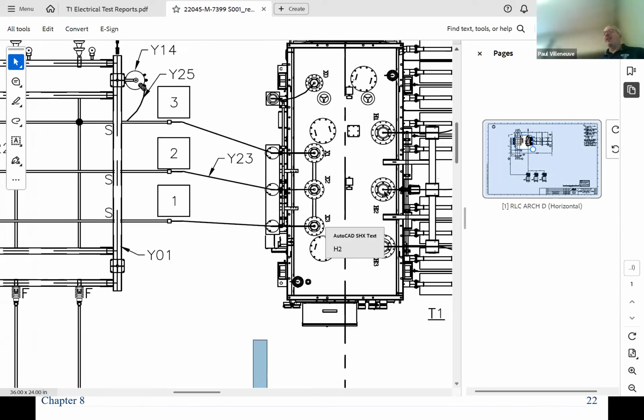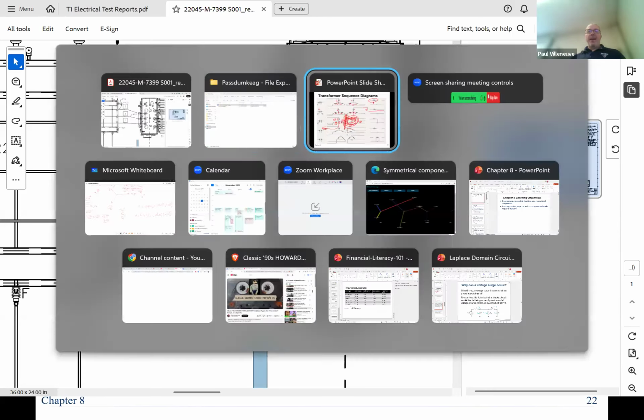Look at the spacing on this side of the bushings compared to over here. This is spaced out a lot more than over here, right? So it's reasonable to assume that the H windings would be the high voltage windings, the high voltage bushings. Look at the neutral. There's an actual connection to ground right here. So that's how most generating stations are built, to be grounded. And the transformers are almost always solidly grounded. So that backed us up.